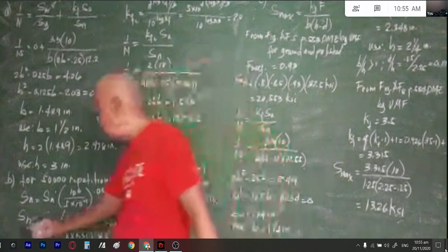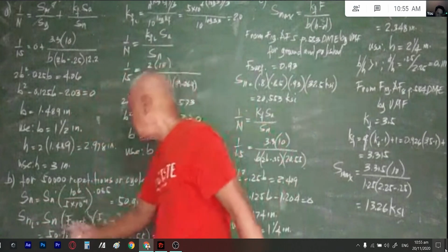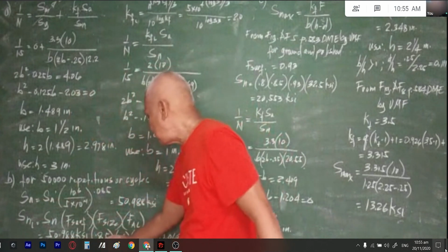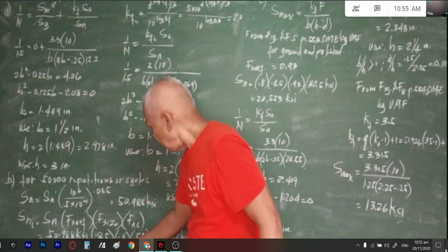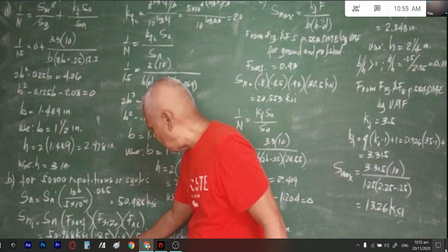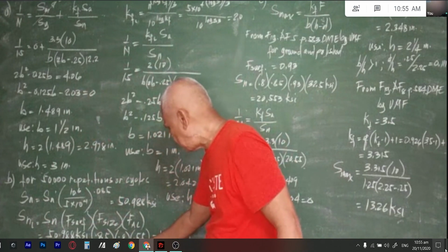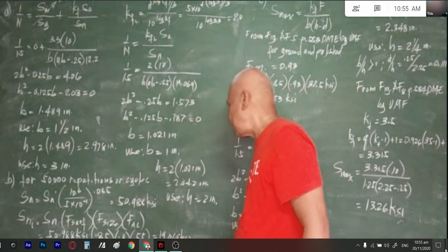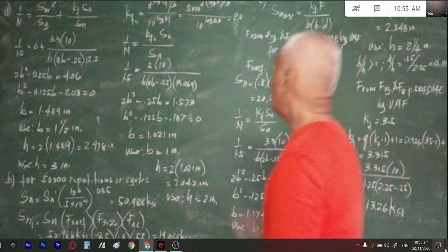So for the endurance strength for limited life, the value we have taken here, 50.988 ksi, multiplied by the size factor, the axial loading factor, and the surface factor, 0.55. That will give us 19.089 ksi.